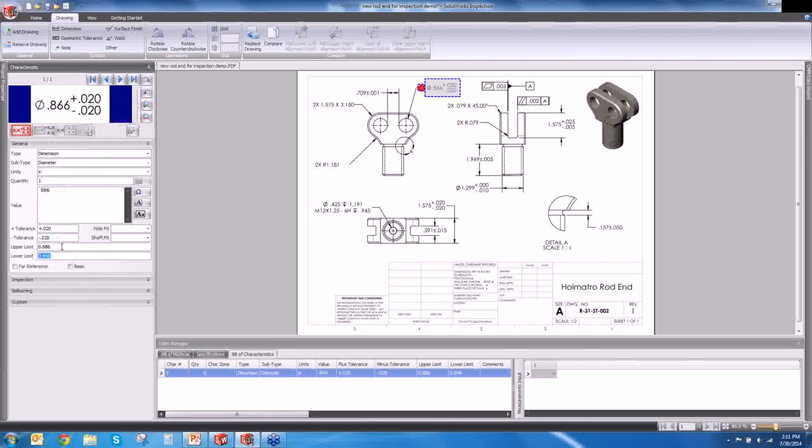So when you're going through and doing your inspections, the software knows that this is the limit that the measurement can be in. Is that good to go, or do we have a problem with an issue with our part? So this is kind of the highlight of the OCR, the optical recognition within the SOLIDWORKS Inspection. It makes it so that you don't have to type in this data every single time you're trying to create an inspection line item. So I'm going to go ahead and do the same thing.